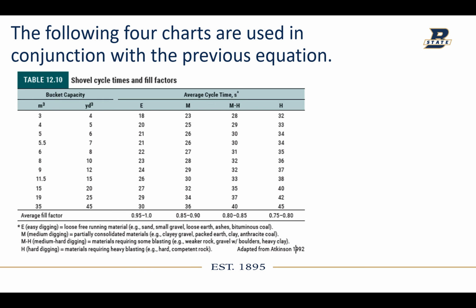The following four charts are used in conjunction with those previous equations, and this gives you average cycle times for different digging, with also average fill factors, okay?